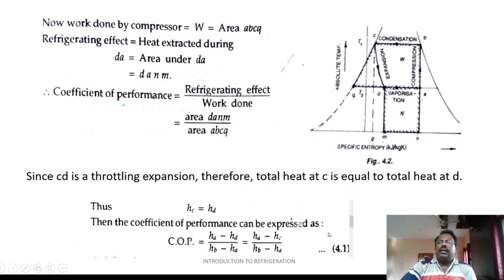That is, the vapor needed after compression is a dry vapor in order to have good volumetric efficiency and good mechanical efficiency and low effect on the compressor. Okay.